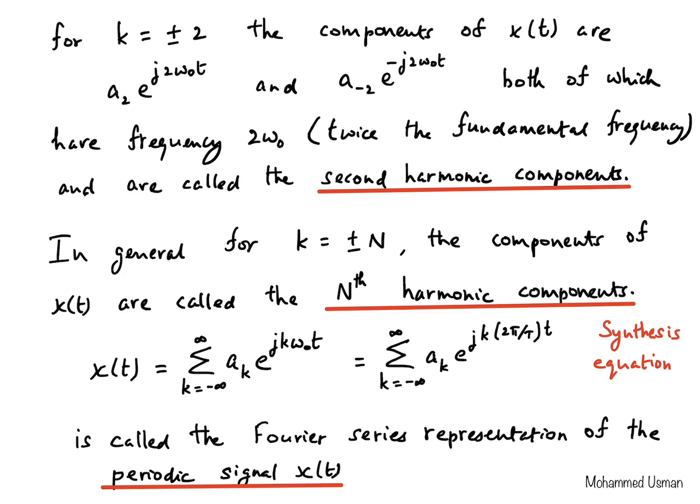So to summarize, what we have discussed in today's lecture is the idea of being able to represent a signal in terms of some basic signal. Previously, we had seen how we can represent a signal in terms of the unit impulse function. And today we have seen how we can represent signals, both in continuous time and in discrete time, as a linear combination of complex exponential signals.